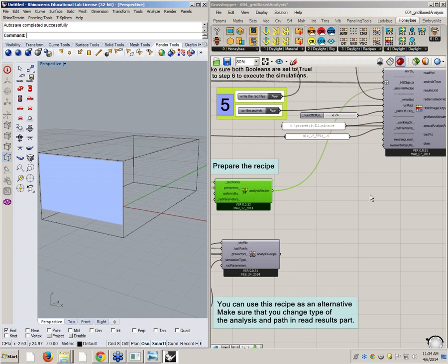Solved. So something happened when I connected this, like you had multiple windows pop up, right? That's fine, because it doesn't say no light. It says there's no light source, right? Because it's searching for your light source, and right now the light source is the sky. It's just giving you a warning that there is no light source. It means there is no light material inside, because we don't have anything with light material assigned. There's a material in Radiance called light. Like you have glass, you have light. That's a warning, it doesn't matter.